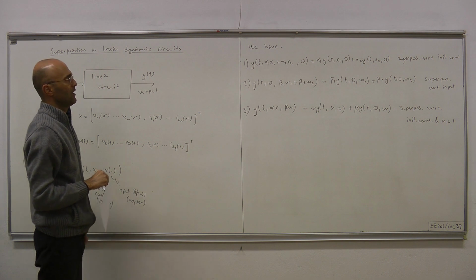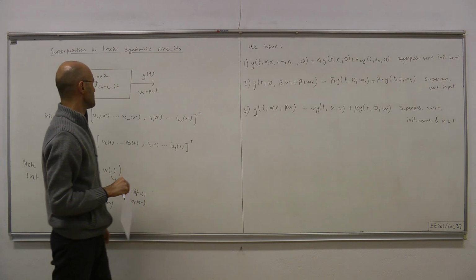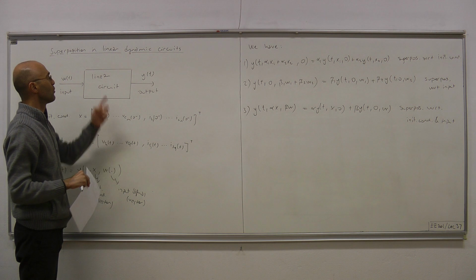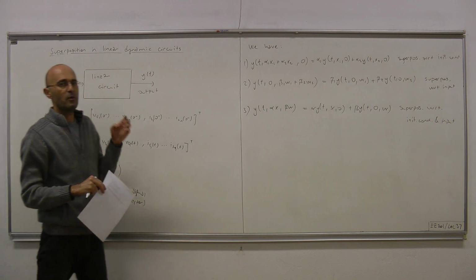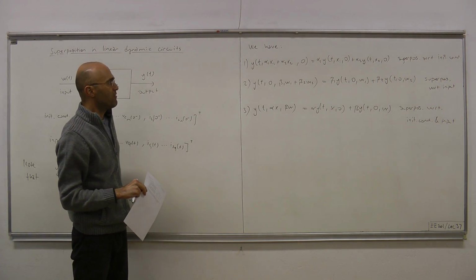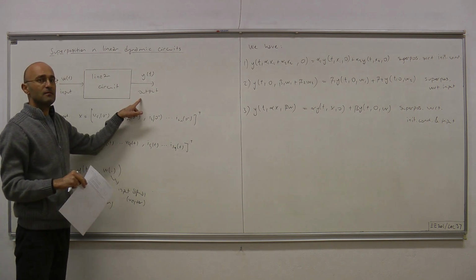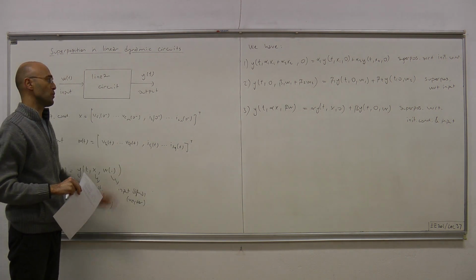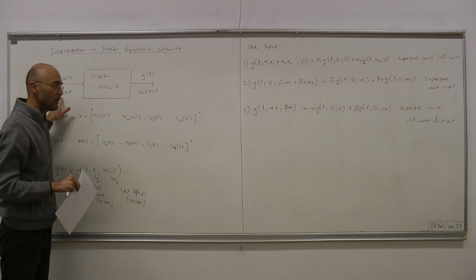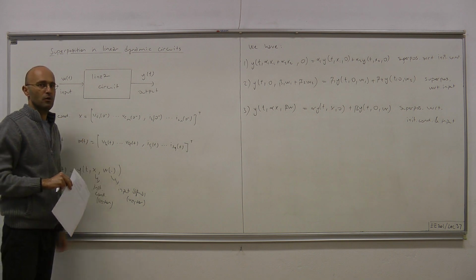Okay. So therefore, superposition is extended for dynamic circuits in the following way. And the extension is due to the fact that the output, unlike resistive circuits, not only depends on the input, but also depends on the initial conditions.